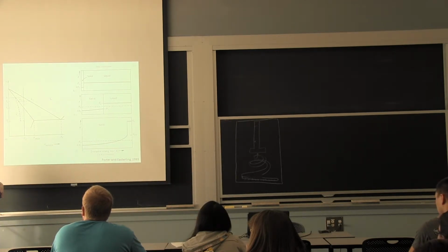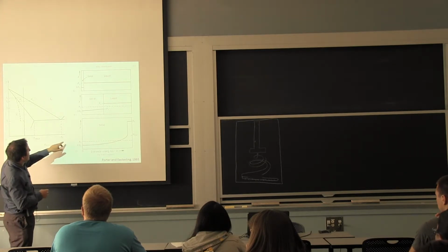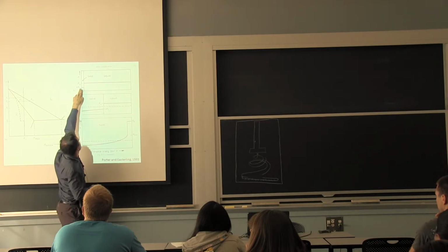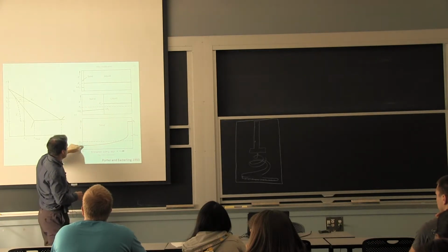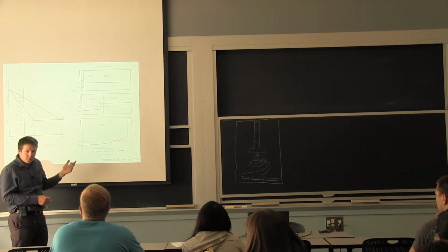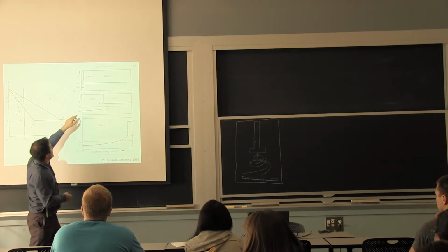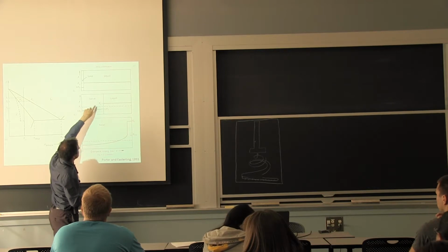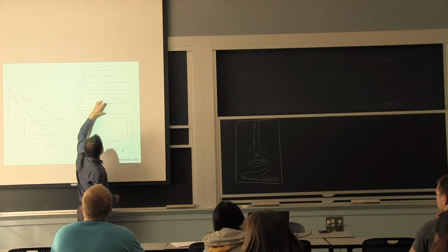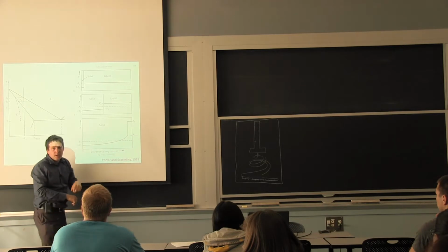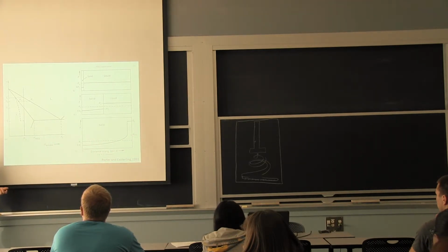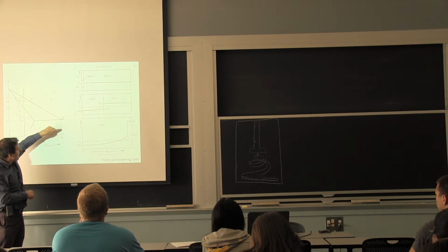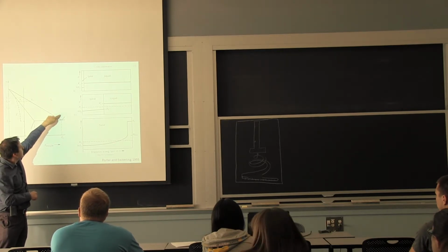But this here is still, regardless of the time that you take, even probably it's fair to say the slower you go, the more it's going to segregate here, because you start with that composition here, and it's not going to change after the fact because it's very slow to diffuse into the solid as opposed to the liquid. So what happens is the liquid composition keeps creeping up. It starts here, it goes higher, keeps going higher. And that's, again, all based on thermodynamics. It doesn't give consideration to kinetics. So again, one way to avoid it is to pick that composition, because you're going to go straight from a liquid to a solid.